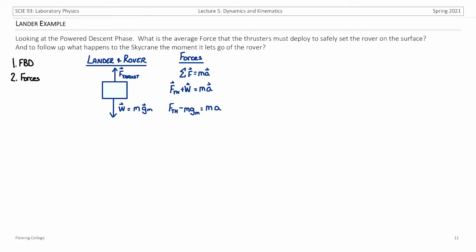Remember, our rover is moving down, which will be a negative displacement with a negative velocity, but the whole time that velocity is getting smaller, which is the equivalent of having a positive acceleration. I'm going to rearrange this equation for thrust, and we can do some factoring just to simplify the equation. But at that point, we're stuck as we have one equation with two unknowns, the amount of thrust we desire and the acceleration we need. So now we switch our focus to motion.